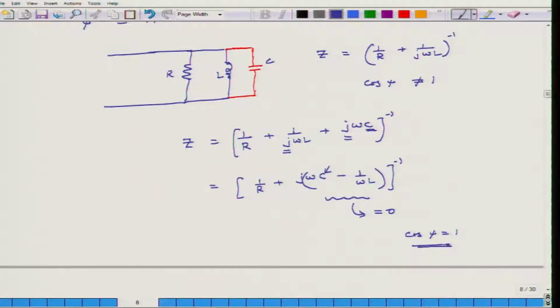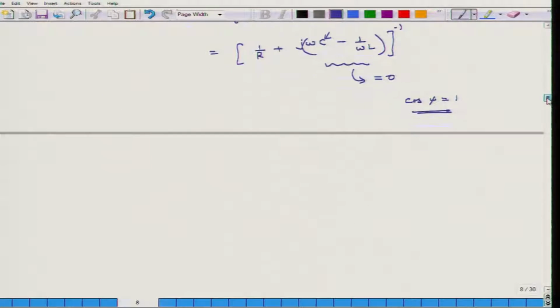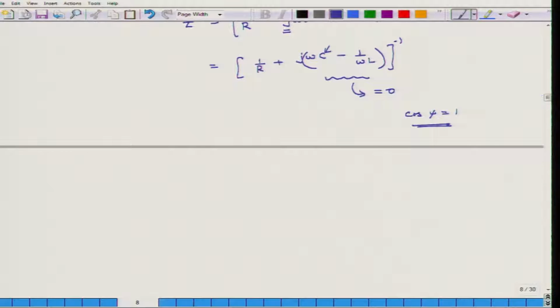By doing this I can set the power factor of my system close to 1, and that helps in the reduction of transmission losses, which helps the economy of the country. So, with that we conclude the discussion on power factor and electrical power, and what we will do now is move to acoustical power.